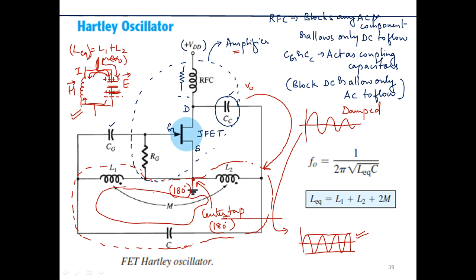Once the electric field gets established, again the charges will be discharged out of the capacitor, and it ensures that again there is a current flow through the inductor. So this is an ongoing process. Okay, fine. And finally, again the feedback, which is VF, the produced output voltage will be fed back to the input of the particular amplifier.